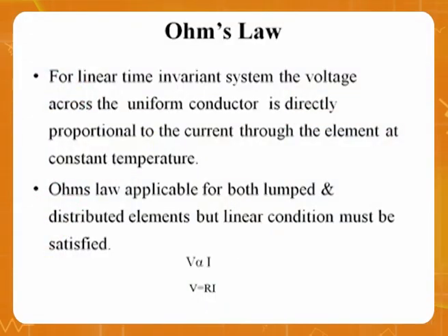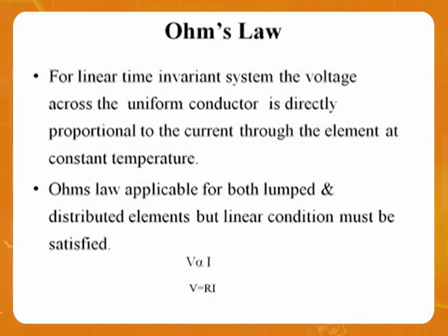Such an element is called a resistor. But sometimes people think that Ohm's law is meant for a resistor. No, Ohm's law is meant for a conductor. Resistance is not an element. It is the property of the conductor. So resistance is the property of a conductor. Therefore, it is defined for a conductor. So Ohm's law is applicable for both lumped and distributed elements, but the linear condition must be maintained. For example, if you go to a transmission line, which is called distributed, you can still apply Ohm's law there. The only difference is it must be linear. So this is about Ohm's law.